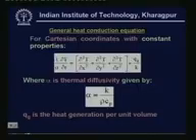So to find the spatial variation of temperature, we have to solve what is known as the general heat conduction equation. So the general heat conduction equation is shown here for Cartesian coordinates with constant thermophysical properties. That means if I am assuming that thermophysical properties such as the thermal conductivity, specific heat, etc. are constant, and if I am applying first law of thermodynamics along with the Fourier's law of heat conduction to a Cartesian coordinate system, we arrive at this general heat conduction equation.